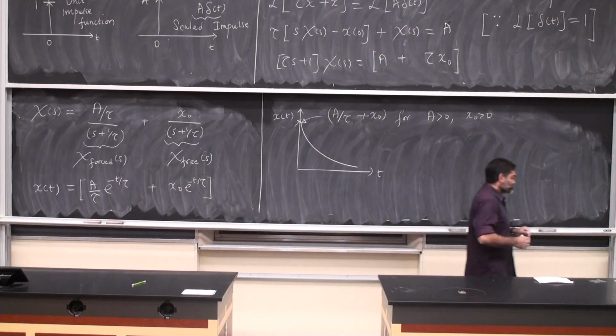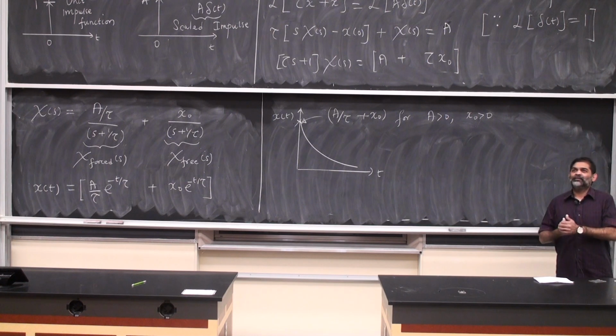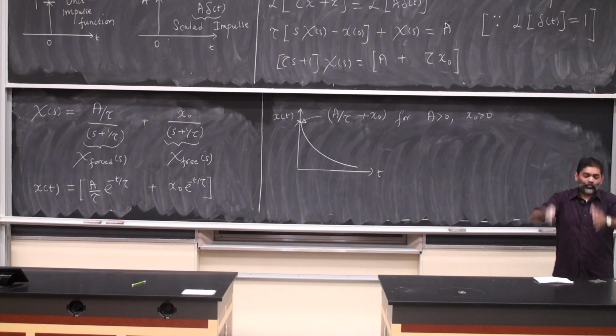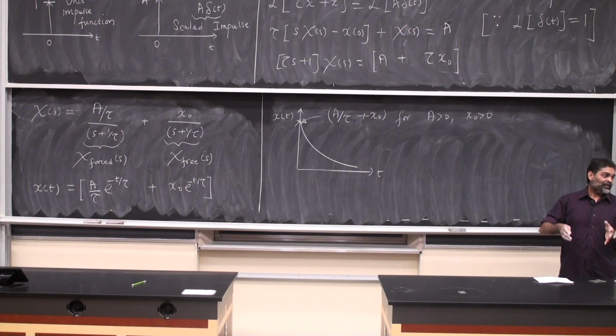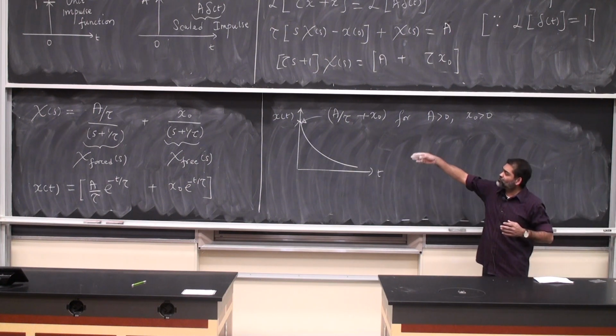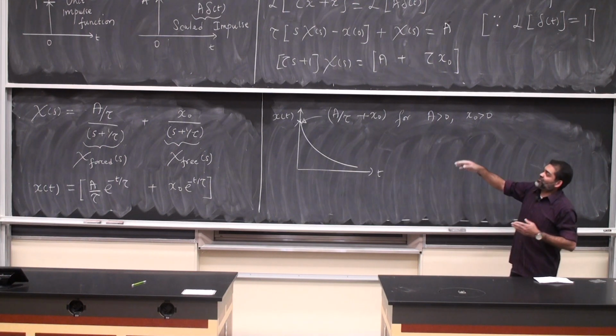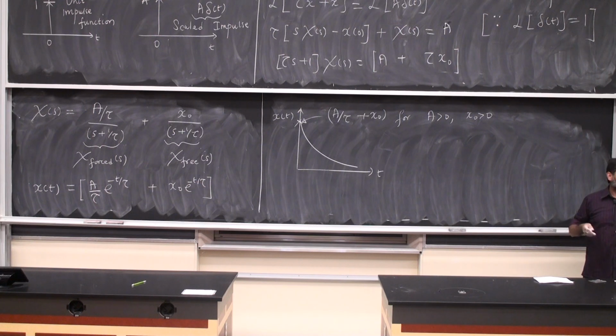Yes, question. So, in the impulse problem, there is no steady state. There is no steady state in a purely impulse setting, right? So typically you can think of a beam with a weight dropping on it. The drop of the weight is an impact on the beam. The beam is going to vibrate for some time and then it's going to stop vibrating. So that's similar to what the system is doing. Of course, here you don't see the vibrations or oscillations. This is an extremely sluggish, damped system, if you think of it that way.